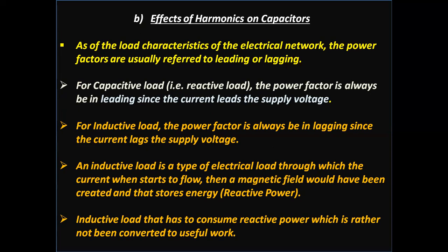An inductive load is a type of electrical load through which, when current starts to flow, a magnetic field is created and then stores energy. That energy is reactive power. Inductive load consumes reactive power, which is not converted to useful work.